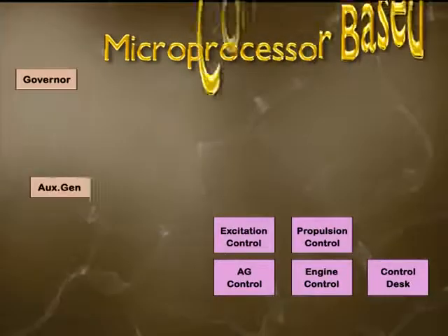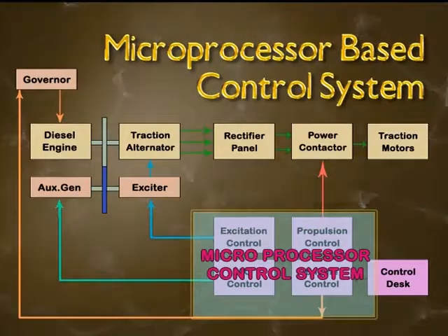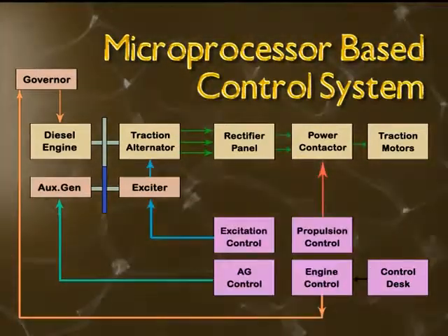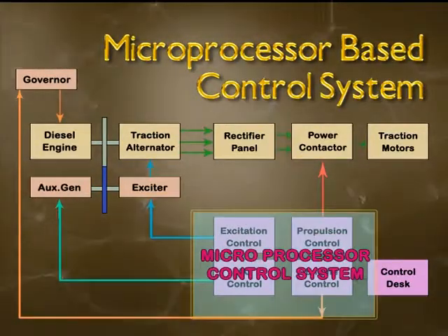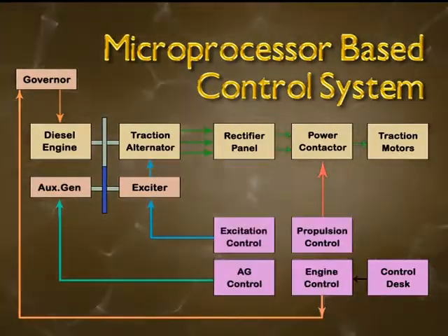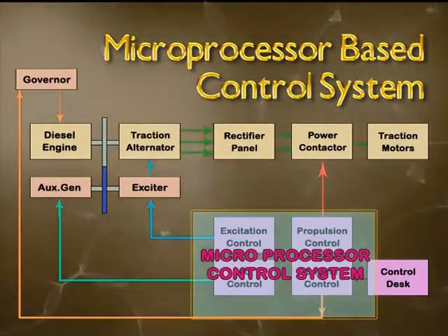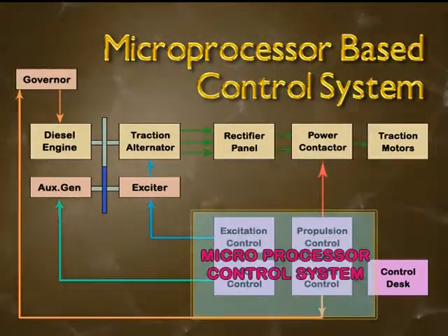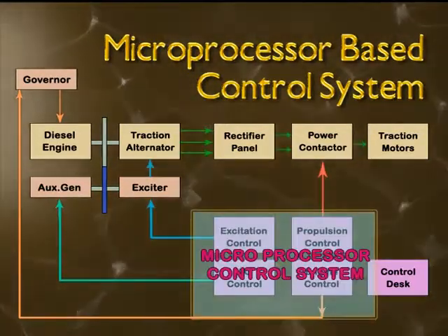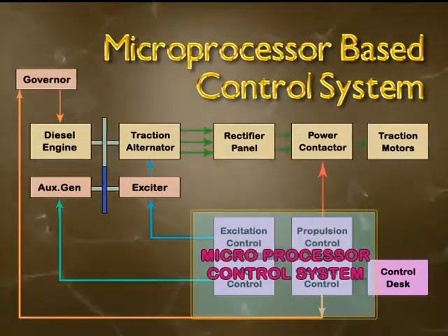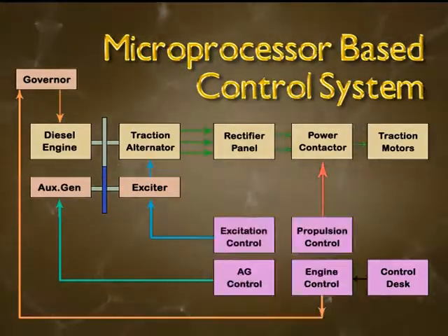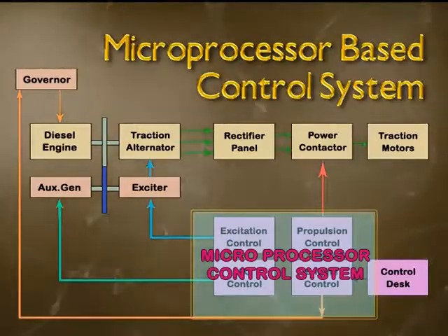The MEP 660 is a complete locomotive control system consisting of engine cranking, loco propulsion control, excitation control, auxiliary generator control, and continuous monitoring of safety devices on the locomotive. Some of the improved features are self-load test of the locomotive and an inbuilt event recorder designed and developed as per RDSO specifications. The MEP 660 loco control system is designed to replace the existing propulsion and E-type excitation system. It eliminates mechanical interlocking and uses a microprocessor to control the locomotive through software logic.